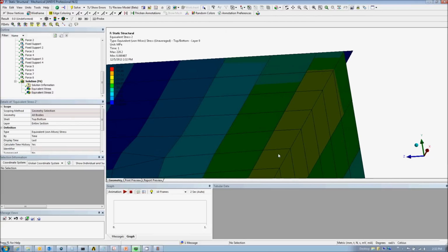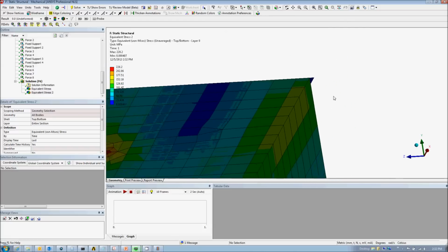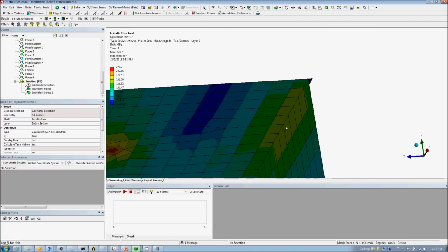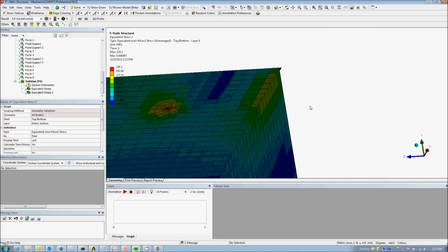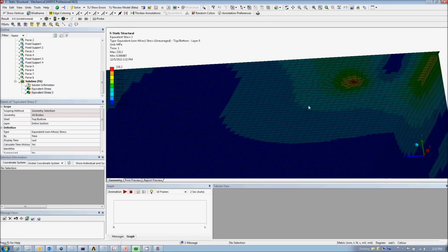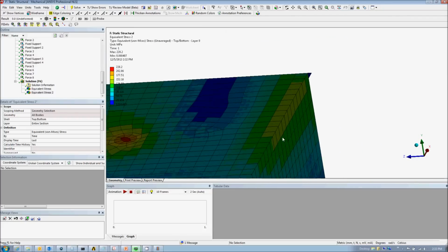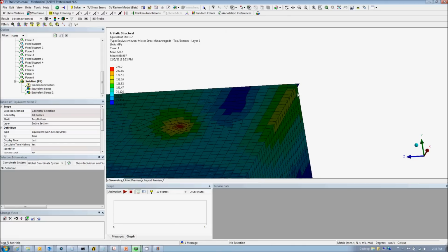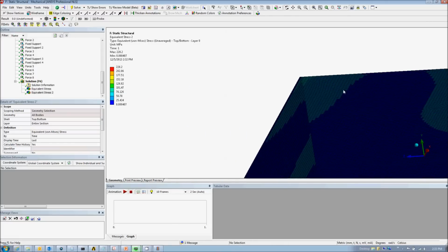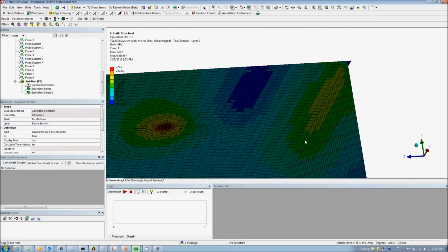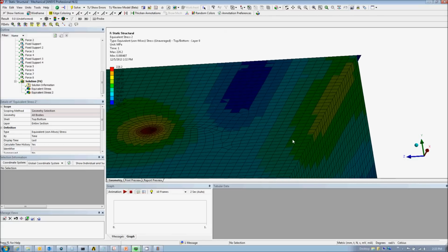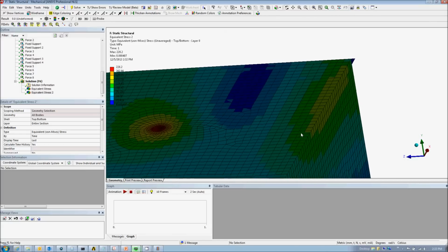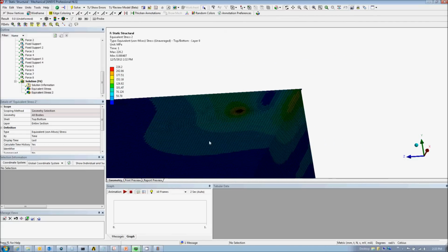To the right I have different mesh sizes, more refined meshes, and we see we still have some adjacent bands or adjacent elements that cover multiple bands. As we continue to refine further, you see the skipping of color bands disappears. Note in this final refinement there was no benefit from the adjacent element color band check.